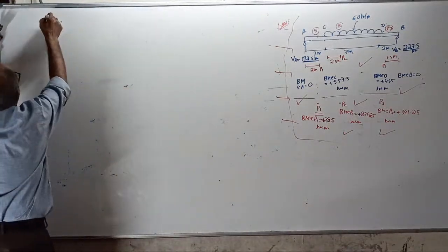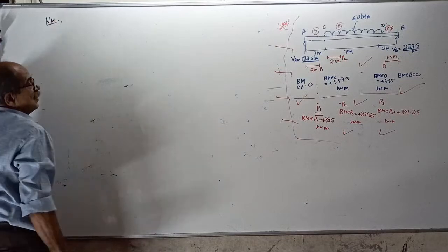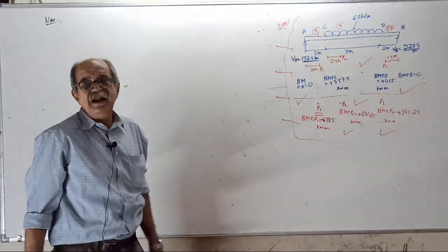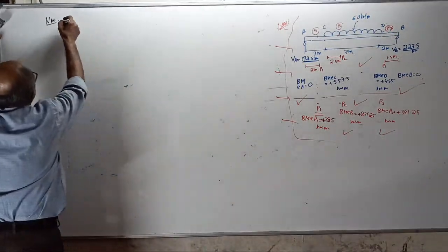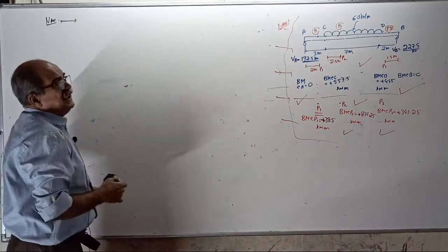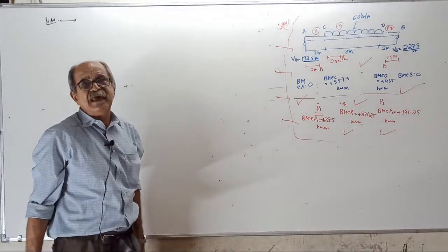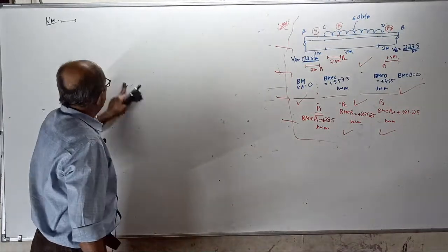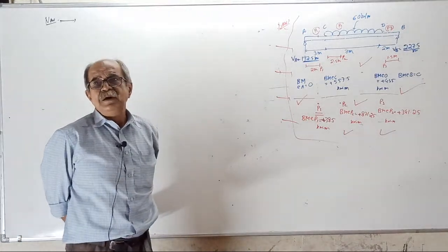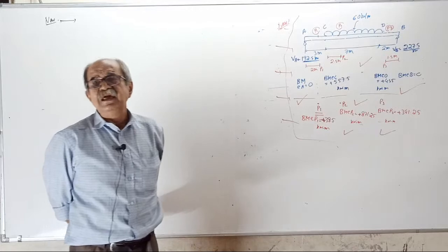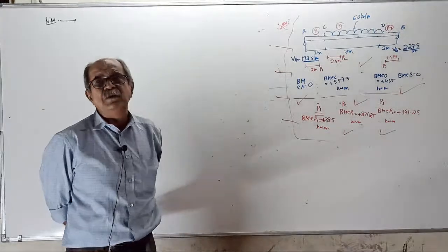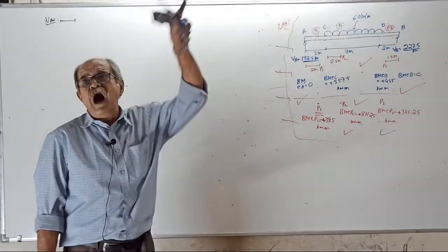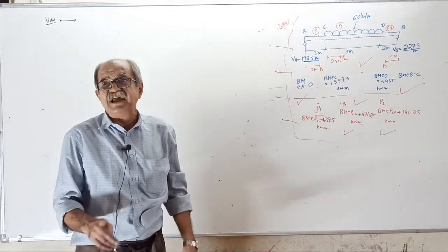Now, you write here. Now, I write black color, that is the combination of blue and red. That is basic. Now, you imagine that this question is required for slope and deflection calculation by Macaulays method. You should write what I am dictating. In the Macaulays method, you have to take an origin at the extreme end. Any extreme end will do. Take a section between the last 2 points on the other side.